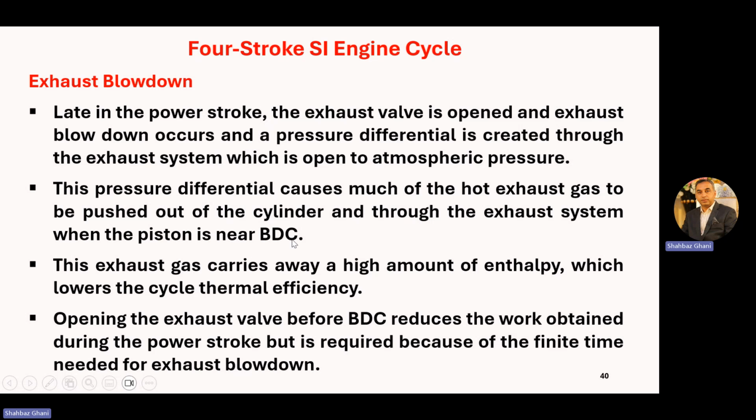When in power stroke, your piston from TDC is coming towards BDC. But before reaching BDC, your exhaust valves open. When exhaust valves open, the hot gases, the exhaust gases, try to escape, and they escape from the exhaust valve. Okay.